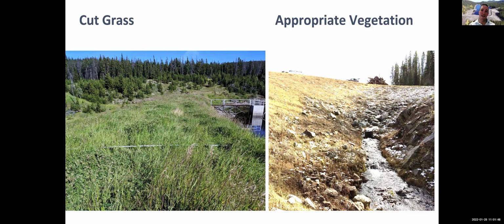Oh, well, the vegetation, they got a spillway over to the left side that kind of heads around and joins up to that low-level outlet. Was that debris in the spillway? And on the upstream bank. And they actually have, similar to what we showed as a better guidance, a point in the reservoir where your log boom does a V. They would have it typically on the sides of the V, right, where we showed where that vegetation was.